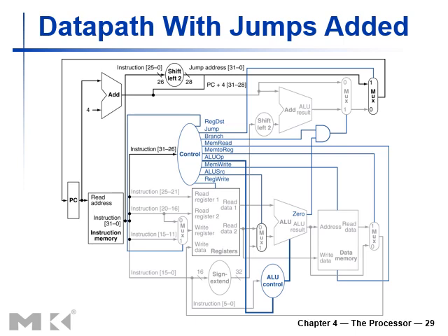The jump instruction is the shortest and the fastest instruction as compared to the other instructions. But due to the single cycle, we have to bear the penalty of wasted time due to the critical path. We only have to fetch the instruction, and we don't have to do anything else. So we don't need any register content. In that particular scenario, no register file is used, no ALU is used, no data memory is used, and no register file write-back is used.